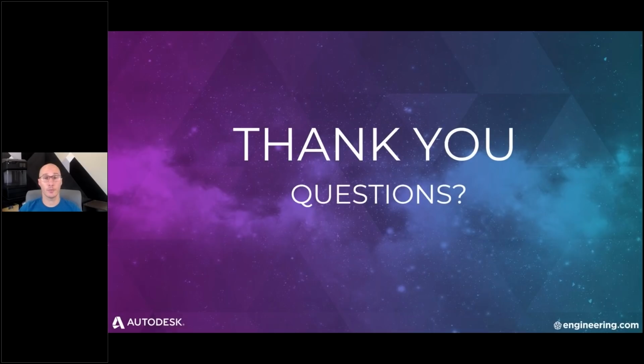When I'm converting scan data into a parametric model or even a dumb solid, I usually start with the faceted approach and then clean up my model. I do have a couple of other techniques that are kind of a hybrid of the two, but I don't recommend just using the face groups option because I think you're going to struggle to get exactly what you're really after. Awesome, thank you.